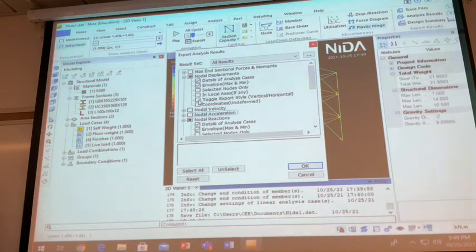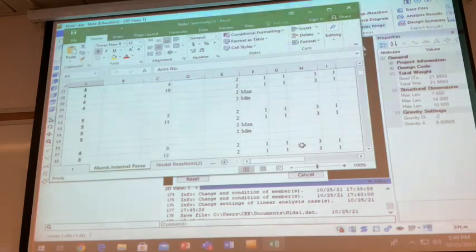But anyway, because this is a rectangular frame, whether you base it on this floor or this floor, the results should be similar, because it should be proportional. So you read the local displacement because you need to calculate the lateral critical to classify the frame. But you need to apply the rotational load. When I say okay, yeah, I get the result.